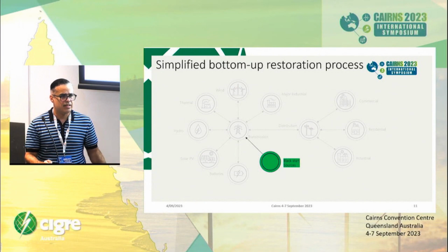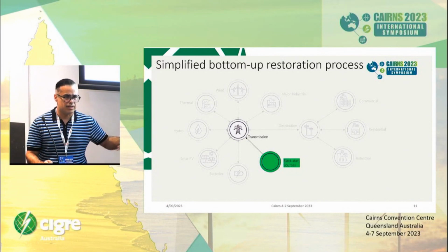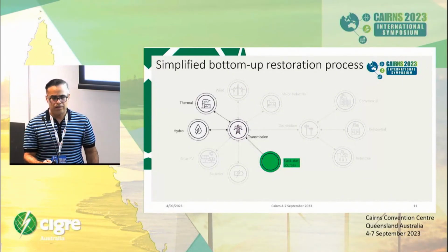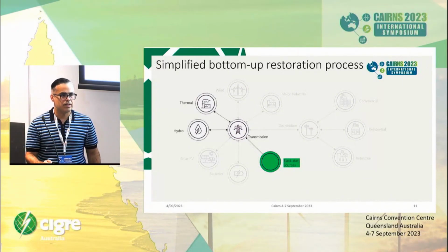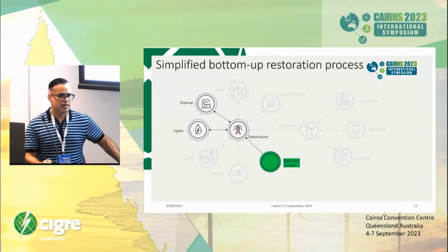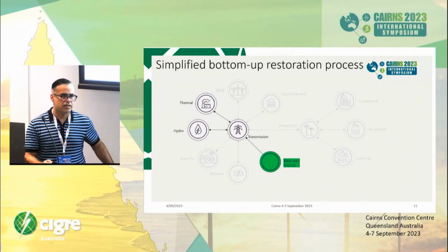It could be anything, typically these days or previously a synchronous generator, and that's to restart part of the transmission network, because that's the fastest way of restarting the power system, and then picking up some other generators. Because you want to expedite the restoration, you want to proceed with energizing the transmission network, which is the backbone of your network, rather than going too much into the distribution network, and that could be basically a trap.